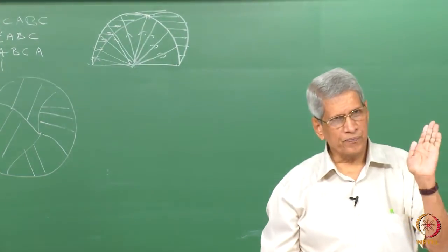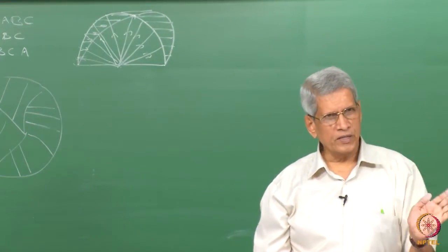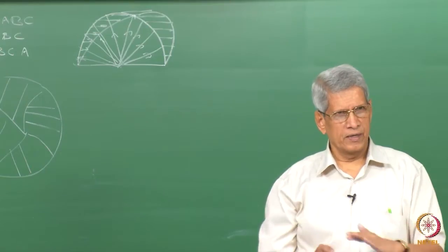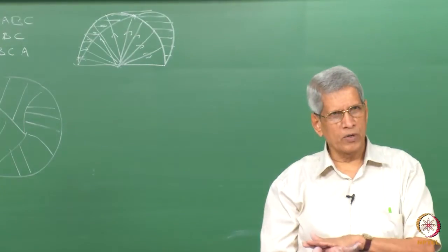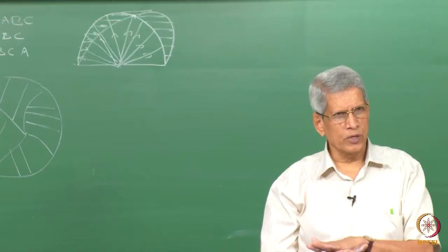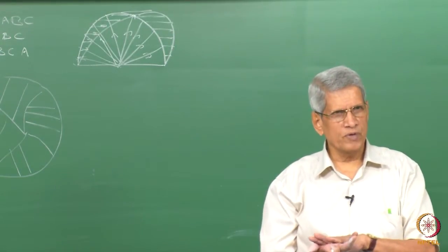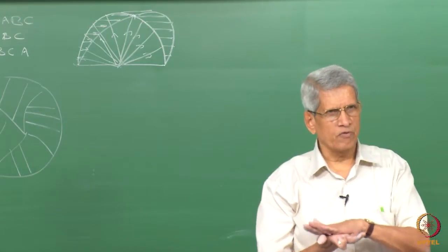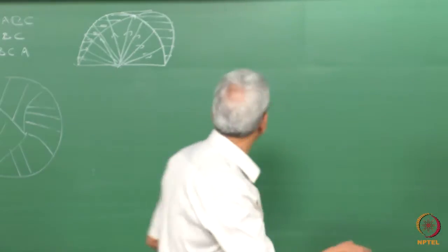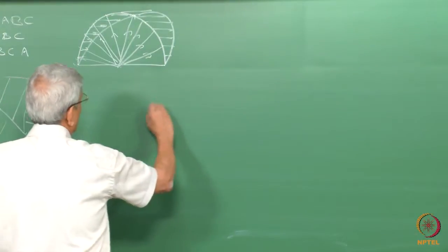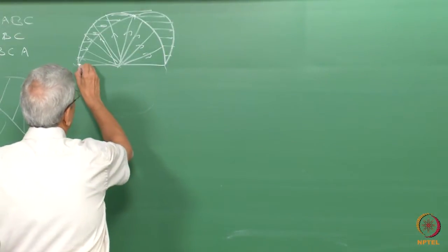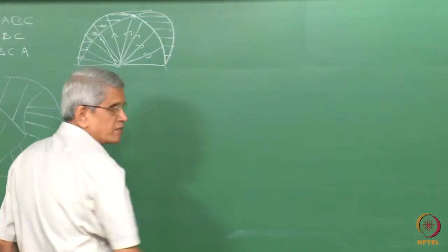After the deformation, there is one particular plane which remains joined together, that is called the composition plane or the twin plane, over which the deformed and the undeformed region are meeting, because you assume that this is the other part of it. So this part with respect to it, when a deformation takes place, has changed.